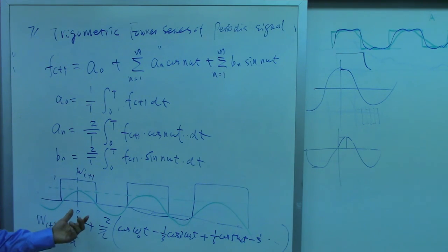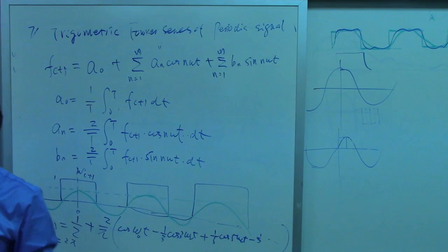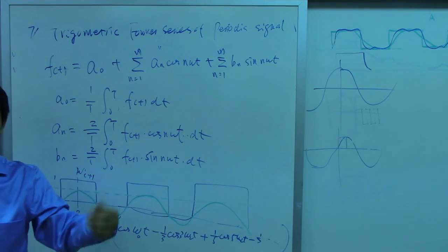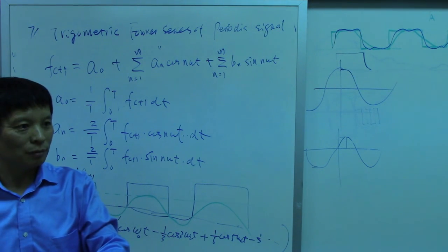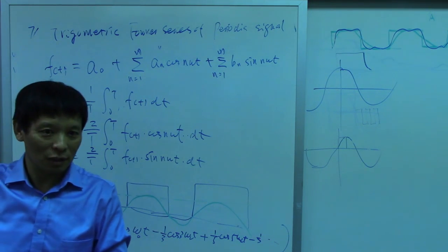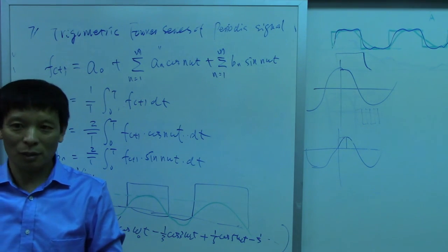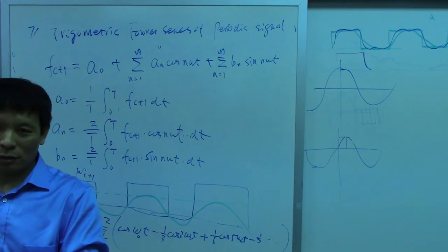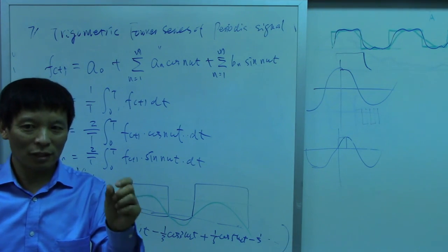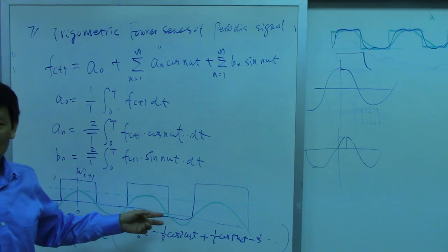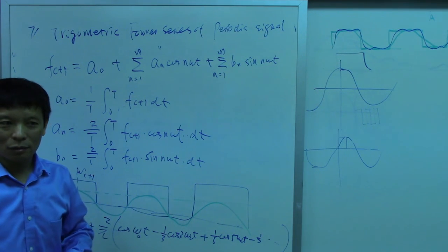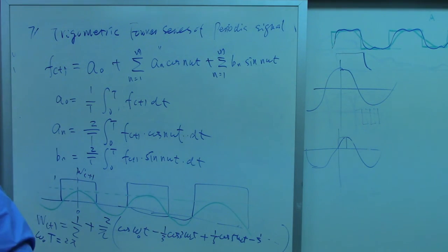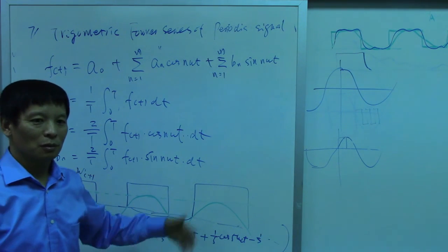And when we discuss the electric digital signals 1, 0, 1, 0, you know when you generate from the oscilloscope, they never rise 90 degrees or fall 90 degrees. That's why we introduced the rise time and the fall time. If you look at the oscilloscope, they have a bandwidth. Some oscilloscope has a bandwidth of 500 meg, some has 100 meg. If you compare two oscilloscopes or spectrum analyzers, no matter what, if the bandwidth is smaller, then the signal will be worse compared to the other. So now we know the fact and we know how to explain this. Later when you design or choose a communication system, you know how to do this.